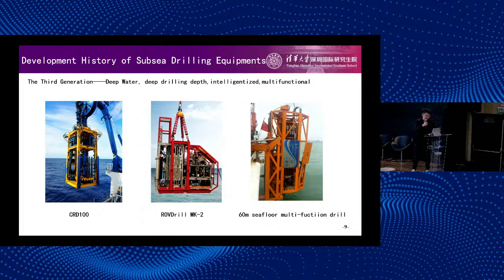Here's another successful commercial seafloor drilling rig from Canyon Offshore, the ROV drill system. It provides a seabed operating drilling module capable of carrying out a range of drilling, sampling, and in situ tests. It can recover samples to 50 meters below the seabed and carry out cone penetration testing, which is called CPT, to over 90 meters.